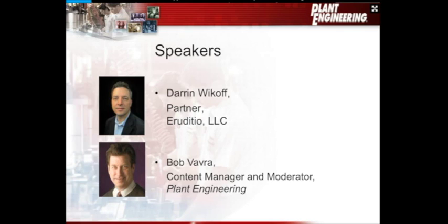The next layer in the criticality analysis is the formal failure modes, effects, and criticality analysis. So now we're drilling into the machines and trying to say, what are the failure mode risks, to get even more clarity around what decisions I need to make.